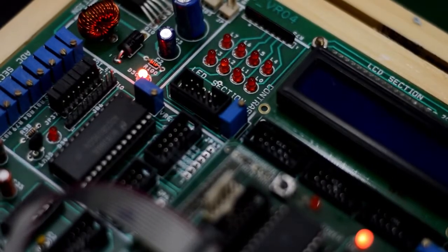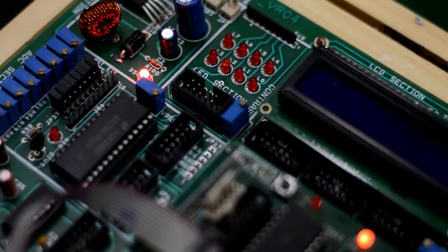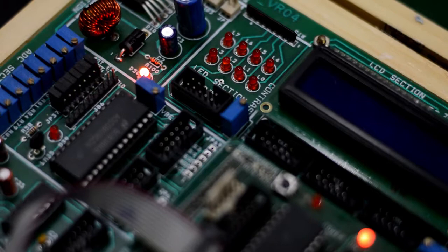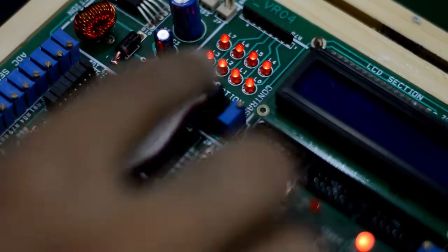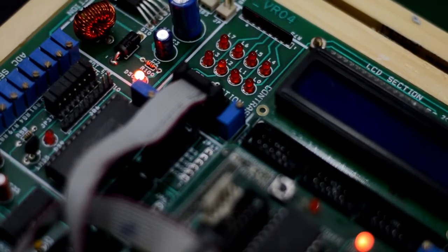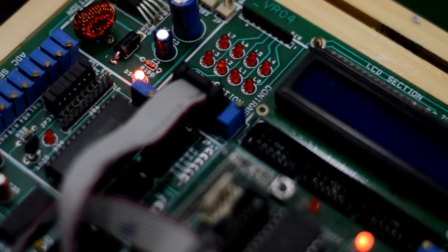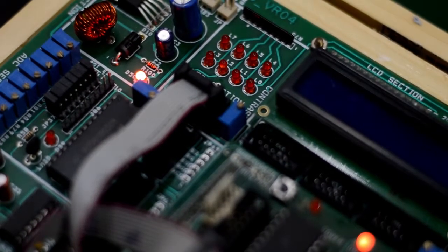So here is the development board, and this is port 2, right? And I have the connector cable. One end of the cable is now connected to port 2. The other end of the cable, I'm connecting it onto the LED section, right? So here it is. You can see the LED is blinking. It remains high for some time. It goes to the off state. It remains in the off state for some time, and then the pattern is repeating. This is what we have written, and we have achieved exactly the same thing, right?